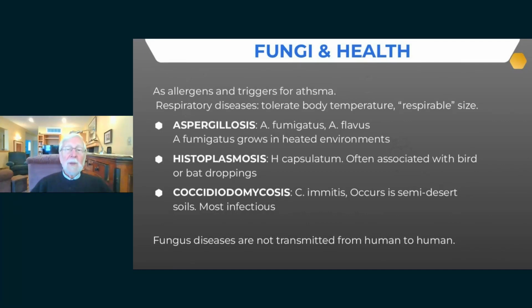So let's look at the next one, histoplasmosis. That is associated with bird and bat droppings. So where do you find those? Certainly in parts of the house where there may be pigeons or bat infestations. Those should be taken very seriously with a lot of respiratory protection, because you don't want to breathe Histoplasma capsulatum.